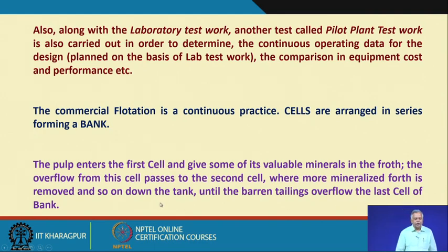That means you try to remove your unwanted material in stages. But along with the material you try to remove, you are also possibly removing some of your wanted materials, because appropriate selectivity, appropriate separation in one stage may not be possible, because you have to have a compromise with the economics of the process.